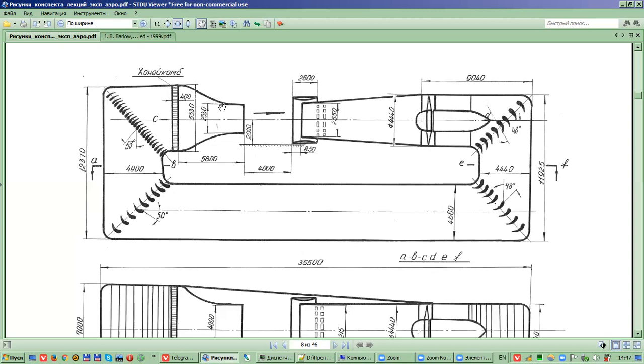Also in the contraction section, larger vortices become smaller, because when you contract the area, the size of vortices also scales down. In a low turbulence wind tunnel, we have a very high contraction ratio, like 10:1. In a high turbulence wind tunnel, we have a moderate contraction ratio, maybe 3:1, 4:1.